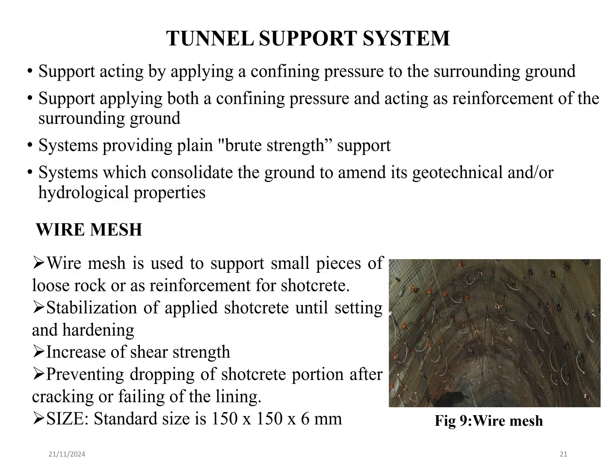Tunnel support system. Additional support measures such as wire mesh, steel ribs, or lattice girders are installed to reinforce the tunnel structure. These supports help to distribute the load and provide additional stability to the tunnel.